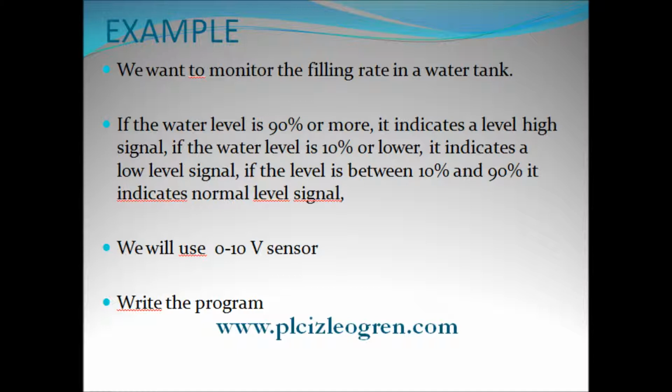Before engaging that, you have to check the pressured air system. Maybe when the system is offline, the pressure drops because of air leakage. Or the pressure can drop during revision periods. Before you engage the system, of course, you need to check these. Let's say your pressure here dropped below 10%. I mean it dropped below 10 bars and your command room, or where your operator is based, had received a low level signal.